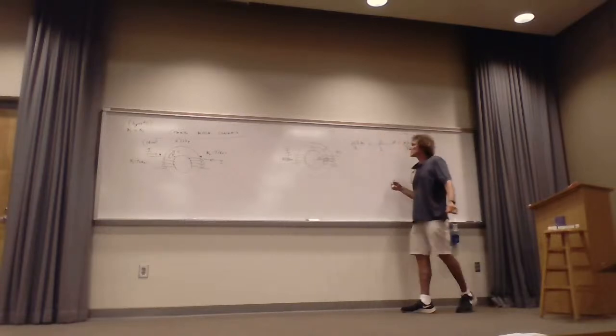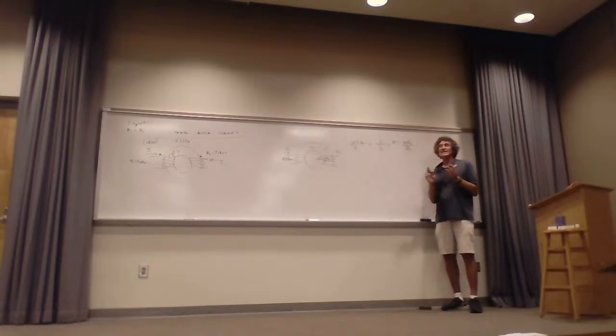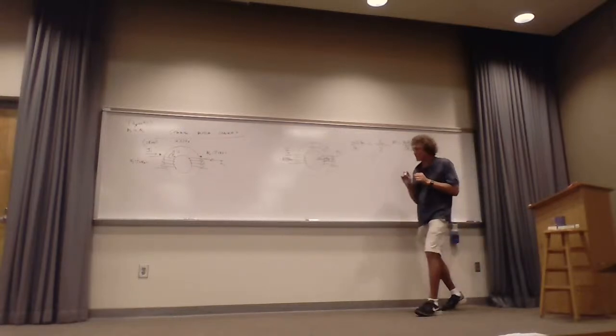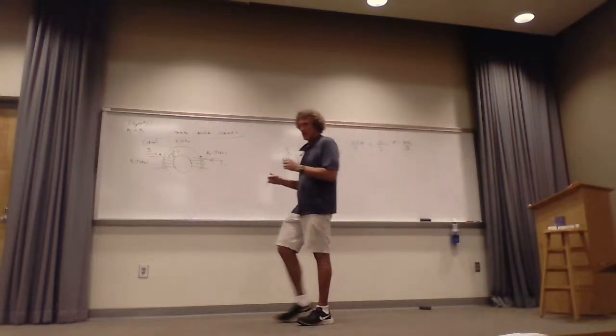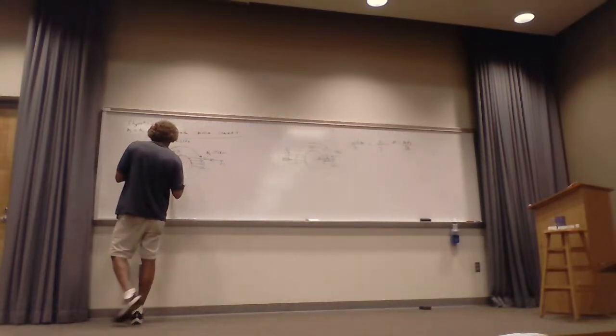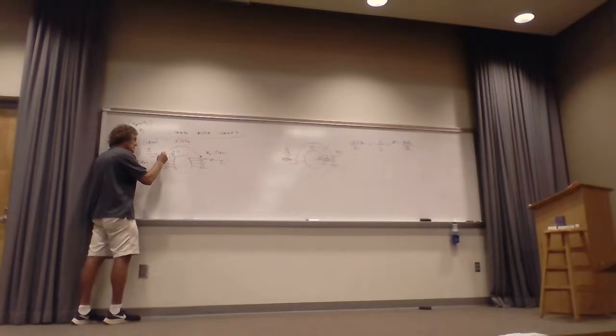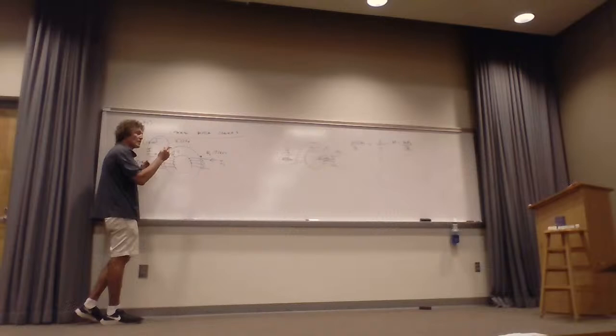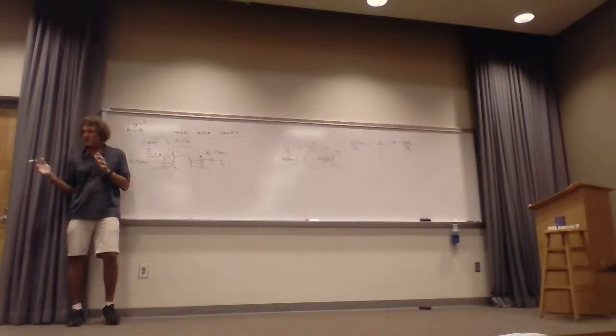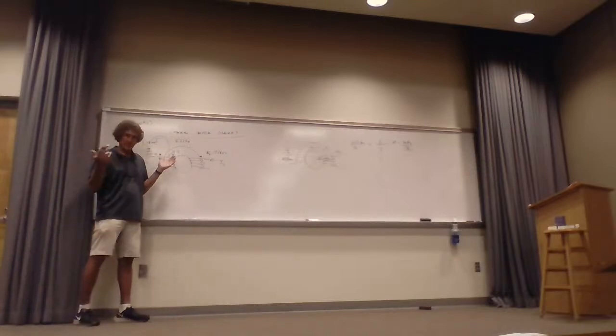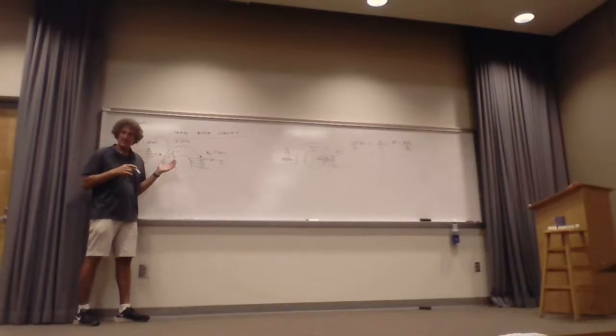You'll notice that the mutual and the self inductance would be identical, technically, if the number of turns are the same. Do y'all see that? Now here's the truth. They're never quite exactly the same, and here's why. They're not showing you this, but there are fringing fields. If you took a look at a B field line, there would be one that comes outside there. So not all the B field is related to the flux, the integral of the B field over the cross sections.